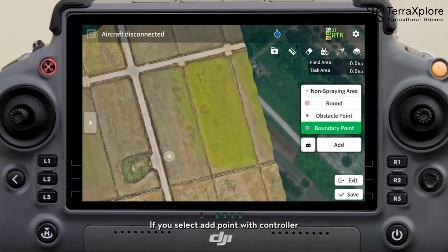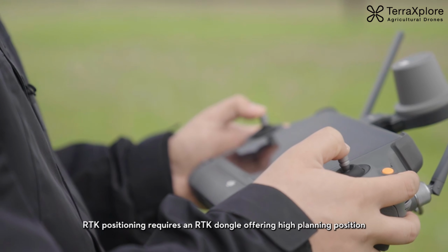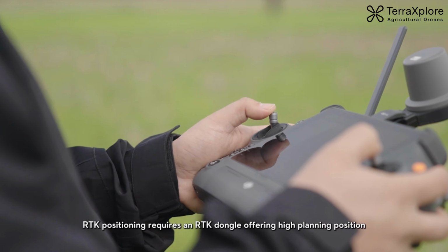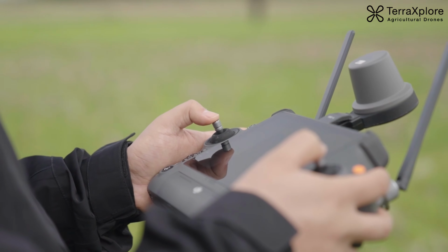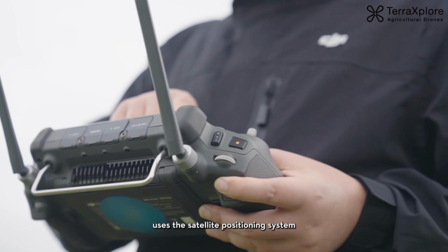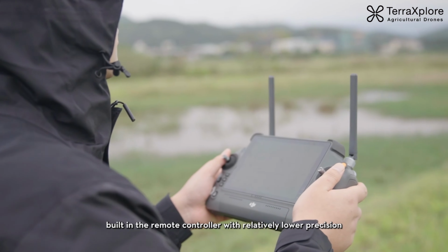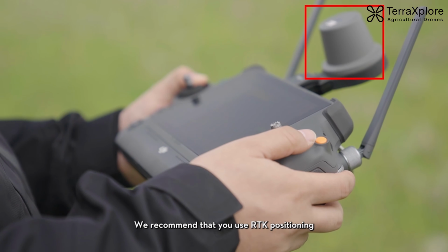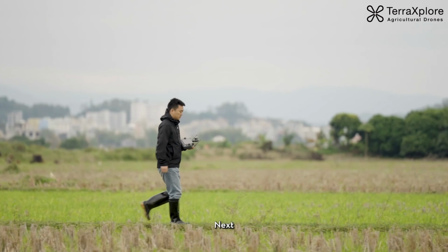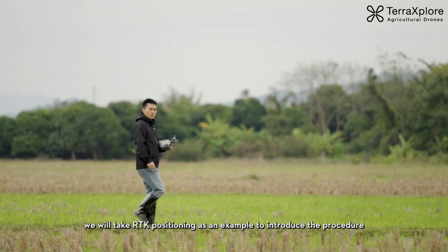If you select add point with controller, you can further choose to use RTK positioning or satellite positioning. RTK positioning requires an RTK dongle, offering high planning precision. Satellite positioning, on the other hand, uses the satellite positioning system built in the remote controller with relatively lower precision. We recommend that you use RTK positioning. Next, we will take RTK positioning as an example to introduce the procedure.